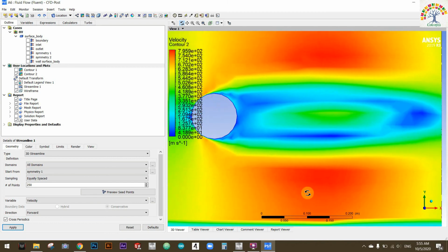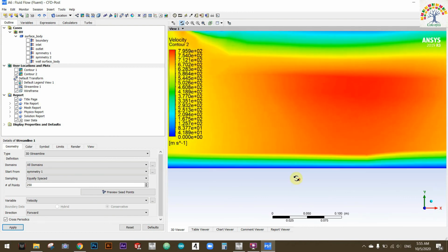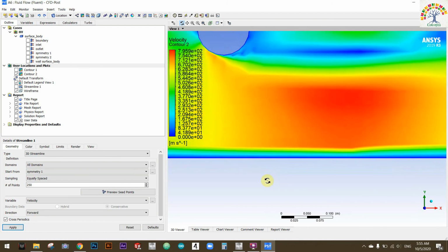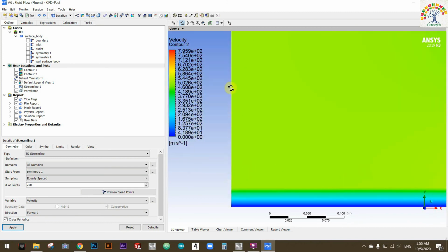And around the boundaries, what is happening over here? What is happening over here? This is the boundary layer. Yeah? Not this boundary layer. This one. It sticks to the domain walls. And as we go away from the domain walls, the velocity gets bigger and bigger until it gets to the normal velocity that we entered. Look at it over here. The velocity we entered is 500 meter per second. This green region is 500 meter per second, and this is 0. So it goes from 0 to 500 meter per second quite quickly. This is the boundary layer thickness over here. This whole thing.